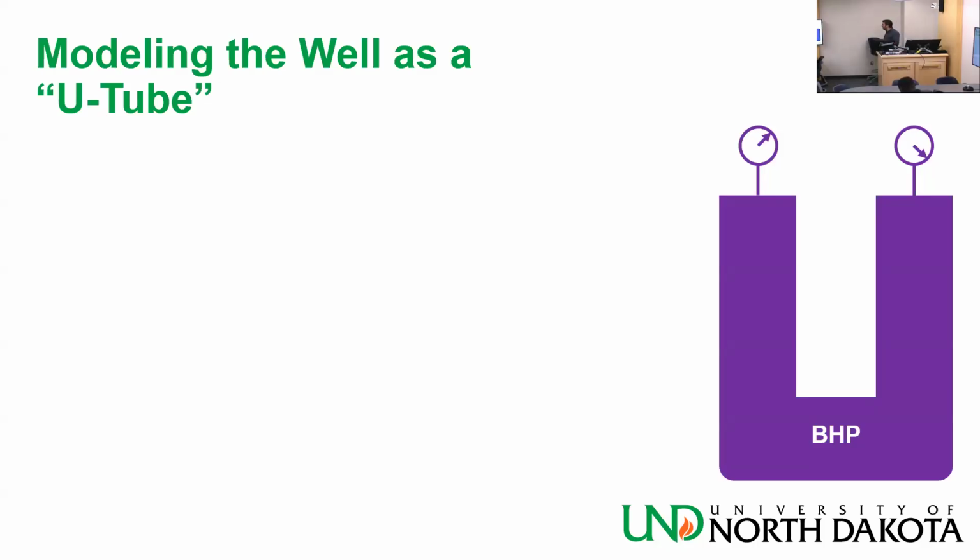The U-tube model is basically a model for how the pressures vary throughout the well, inside the tubular, inside the drill string and outside of the drill string. And you are going to use it to derive the equations that you need to solve a problem. So it's applicable for basically everything, even when you have fluids mixing with each other, then you need to make some corrections.